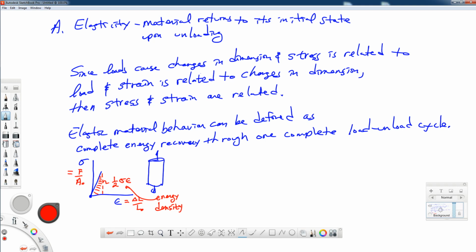Now we do have to stop here and think about this a little bit. Does any mechanical process really completely 100% involve absolutely no energy losses? Well, no, but things like mechanical springs are very efficient at energy transfer, and you don't lose very much. I am not saying that a material will be exactly the same every time you load it. There are atoms in materials, like metals. There are things called slip systems. And these things, and dislocations in metals in particular, will move atoms around, and things don't exactly go back to where they were before you loaded it.